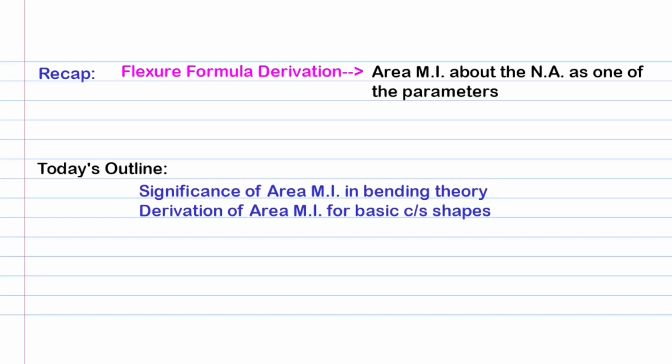The neutral axis coincides with the centroidal axis for initially straight beams, and it separates the cross-section area into two distinct zones, one with tensile bending stresses acting on the longitudinal fibers and the other with compressive bending stresses. The neutral axis or neutral surface in particular does not bear any bending normal stress but only deforms its shape from initially straight to a circular arc in the presence of maximum bending moment.